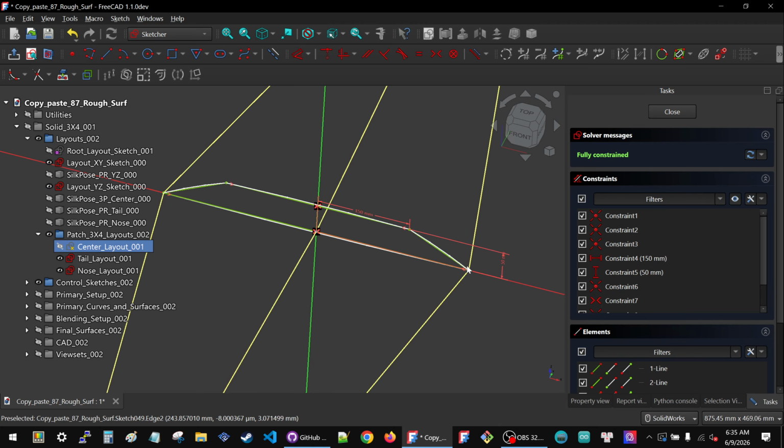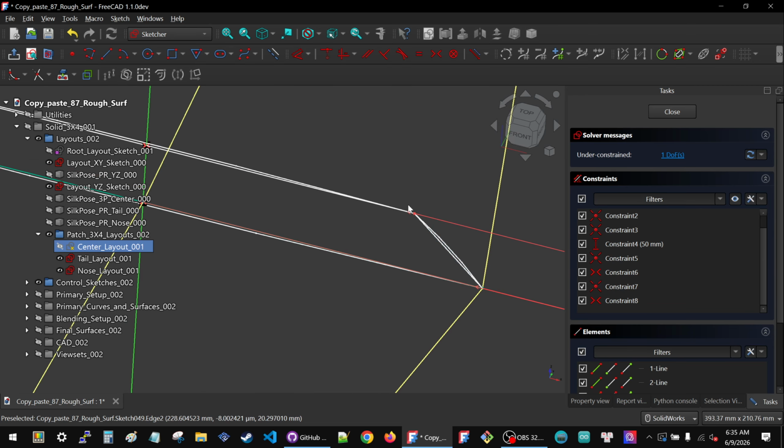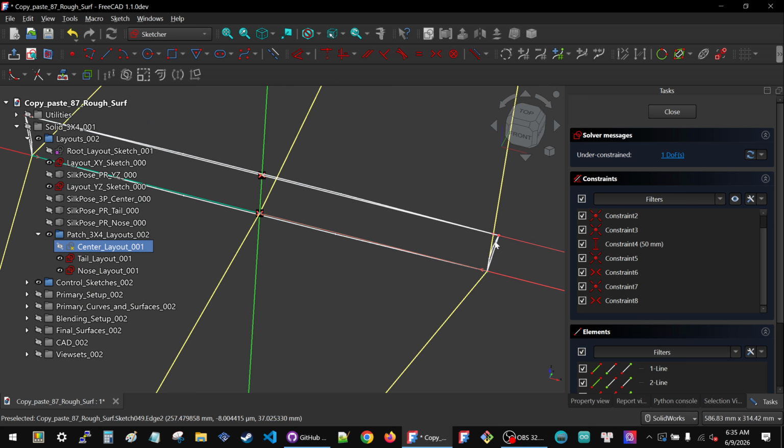So this is 250. I want to go all the way up to 225, but I don't want to do it all at once. Just going to delete the dimension and drag it a little bit out. Drag it in 2 or 3 operations. Just 2 or 3. Nothing too crazy. See, that already flipped these sketches because they're so tiny. Actually, here's what I'm going to do. I'm going to drag them way out so that they definitely get flipped to the inside. And then I'm going to tuck back in so that they stay outside.